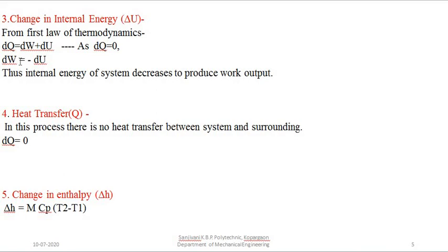Similarly, when you are providing work during compression, that work is the negative work and we are getting an increment in the internal energy. So that will be the positive internal energy. So one term is always negative in this particular equation and both the terms are equivalent to each other. The values are equal. So the total amount of work energy is converted into the total amount of internal energy, and the total amount of internal energy is converted into the total amount of work energy, as the heat transfer is 0. Thus, the internal energy of the system decreases to produce the work output.